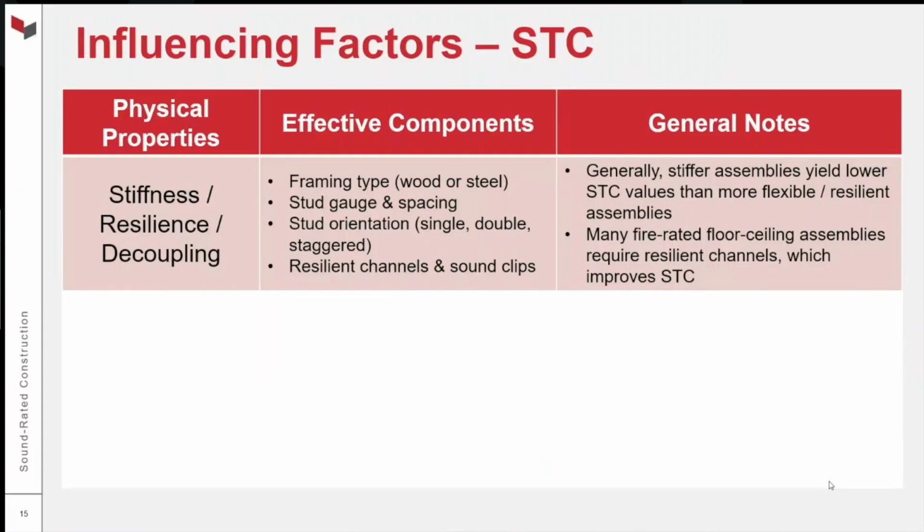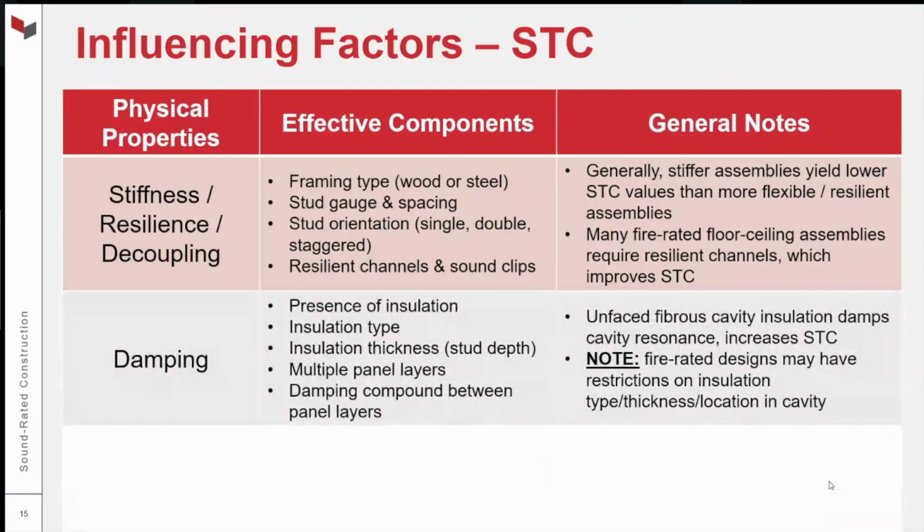The next factor or property we want to talk about is damping. What is damping? Damping is reducing energy, right? Sound is vibration, and the amplitude of that vibration, if you have a high amplitude sound, that is loud sound. So when we think about that STC test and we're blasting sound in excess of 100 decibels, that's high amplitude sound. We want to bring that amplitude down by means of that wall construction, and that is what damping is. Damping is reducing the amplitude. It's removing energy from that incoming sound energy.